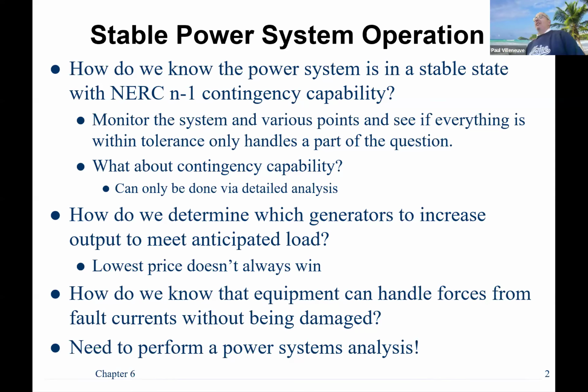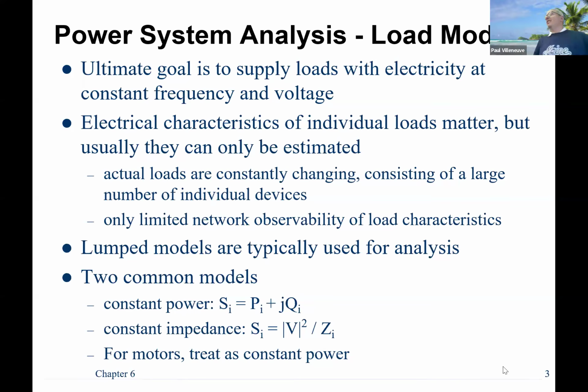So why is that important? Because we want to try to maintain those voltages within reason, and we want to make sure that the frequency is pretty much perfectly 60 hertz. Out of the two, usually frequency is the one that deviates the least. Voltage usually deviates the most. In fact, I've never seen frequency deviate by more than like 0.1 hertz unless some really wacky fault condition happened.